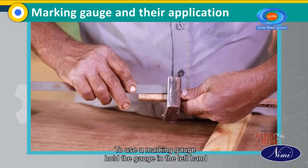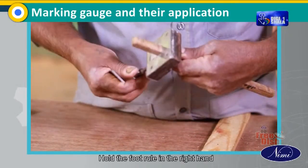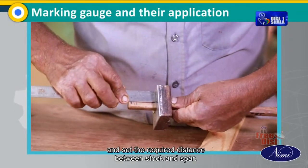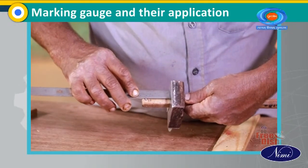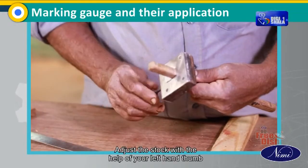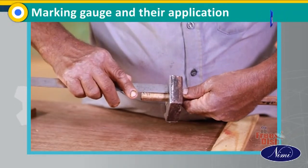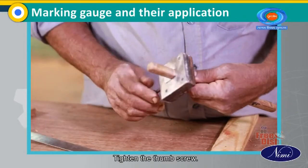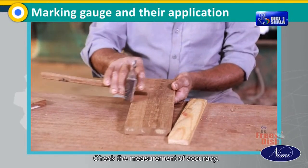To use a marking gauge, hold the gauge in the left hand keeping the spur up. Hold the foot rule in the right hand and set the required distance between stock and spur. Keep the graduation of foot rule in front. Adjust the stock with the help of your left hand thumb and index finger. Now the marking gauge is set. Tighten the thumb screw. Check the measurement of accuracy.